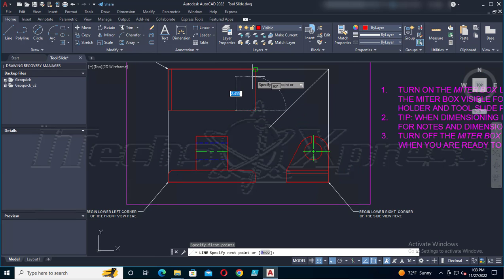Snap to there. And go there. Press enter. And save. Alright, I need to do the same thing with this line here. Get that, that, and then line it up, that, and that. And we'll save. Alright. Now this rectangle here, I need to break it apart, so let's explode it.